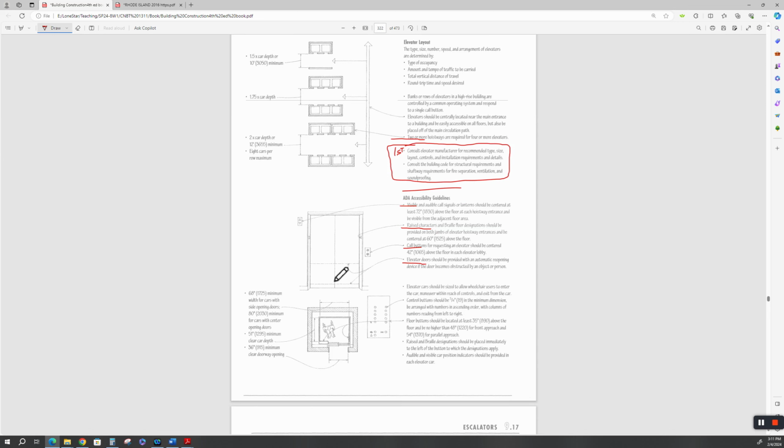The automatic opener didn't work, and it was a bad end for him. And I imagine it was a bad deal for the people in the car with him. But nonetheless, there was some malfunction with the automatic reopening device. Most of them are pressure, and they also use a light, like on an overhead garage door, where you break the beam at the bottom, and then the pressure panel. Some of them have a limit switch, so just the slightest pressure on the door as it's closing retracts the door open again.